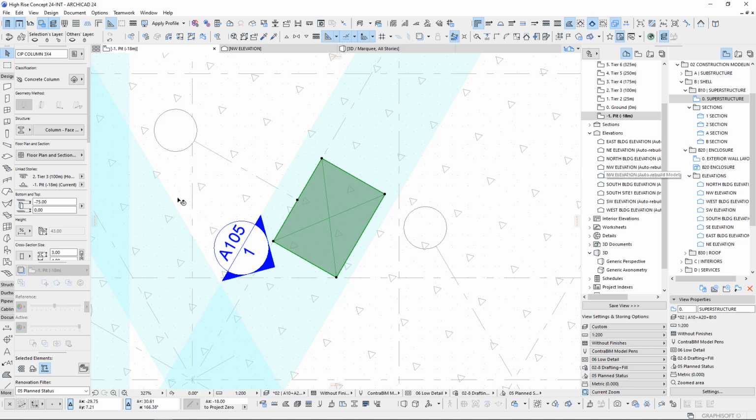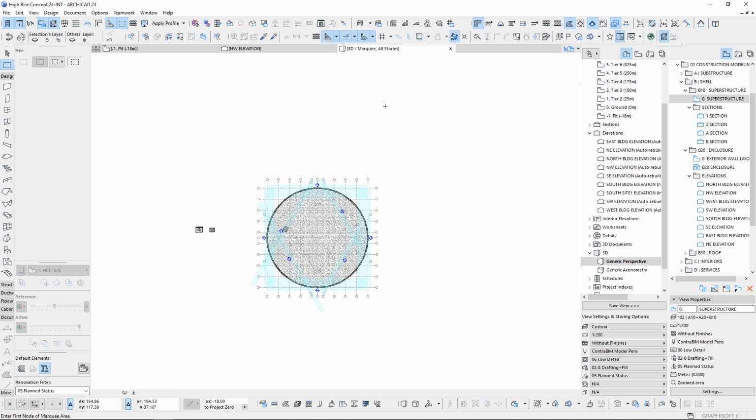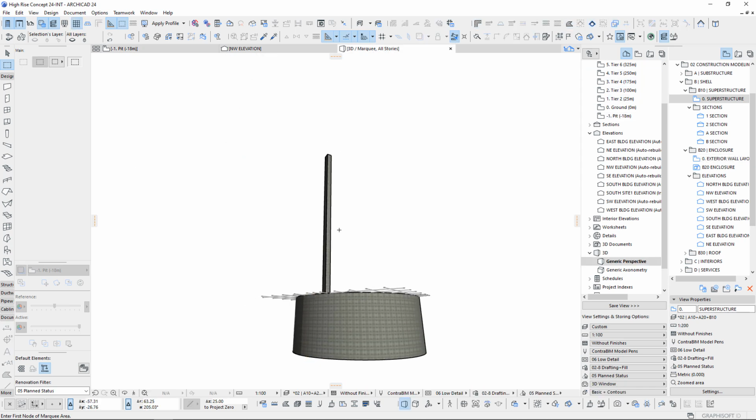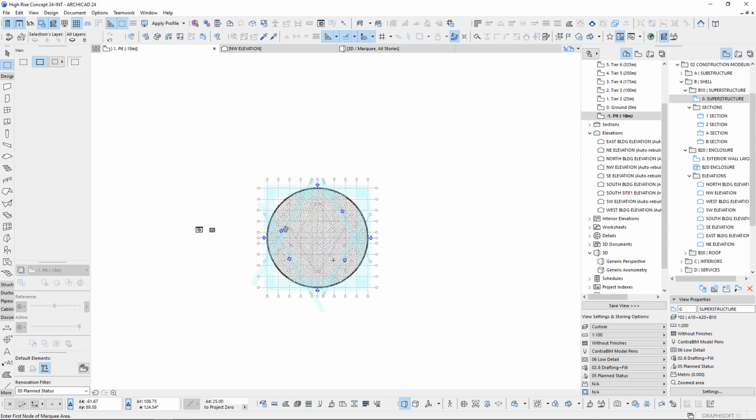We have this one column. It's currently set as the pit, so it's minus 18 to begin with. We can set our top to 100 and we'll just kind of zero that out. So this particular column should go from the pit all the way to, in this case, that tier 3. So let's just check and make sure that we are in the right location on that. So okay, that should work.